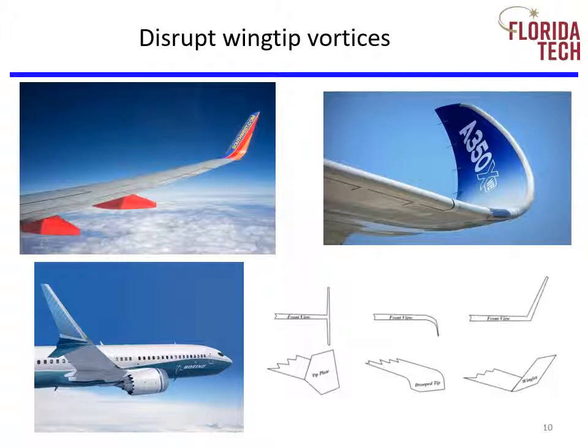End plates, or winglets, are devices on the tips of the wing which particularly disrupt the vortex. This has essentially the same effect as increasing the effective aspect ratio. And you'll see many different approaches to designing end plates. Some go up, some go down, and some do both.